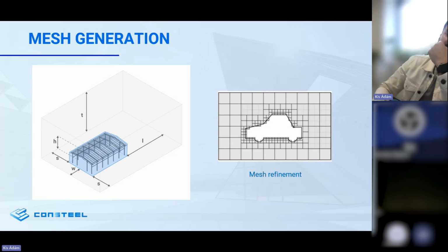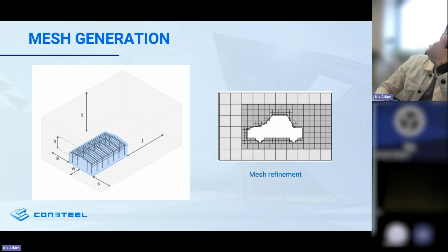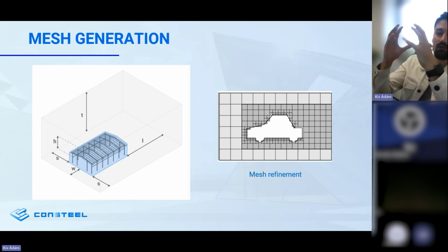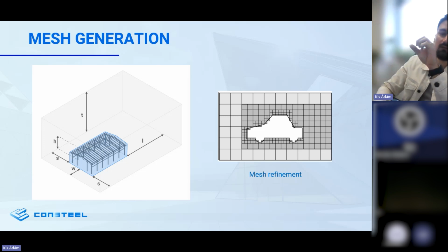But the idea is that we will have a zone or a portion of this computational domain which is much more influential, where the results are really influencing the pressure fields on our structure. Therefore, these zones have to be refined. And what this refinement means is that we have a basic block dimension, let's say at the inlet side of our simulation domain.